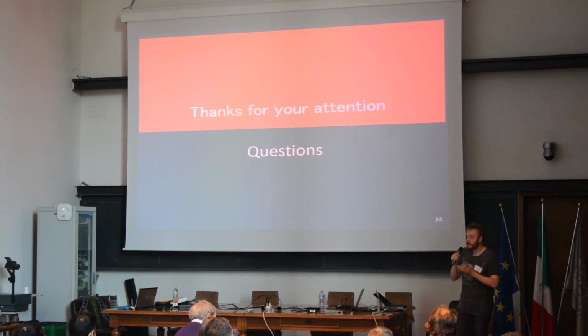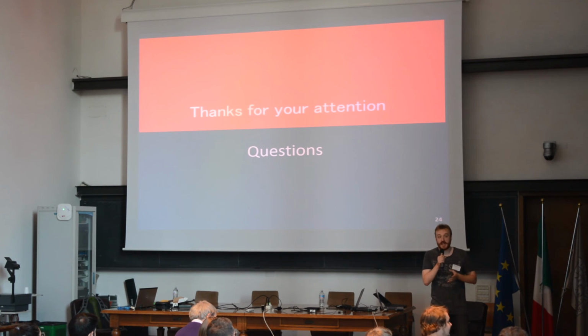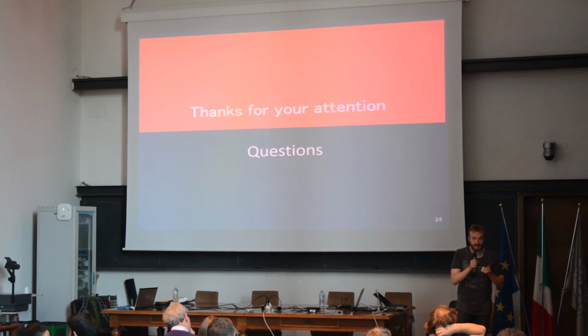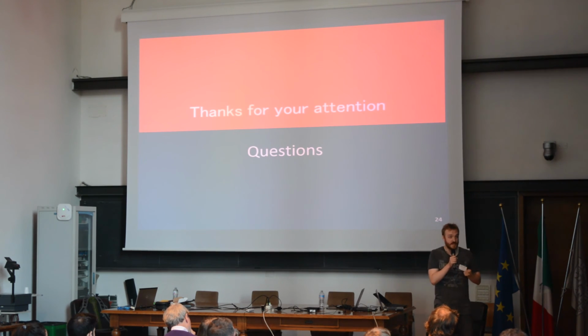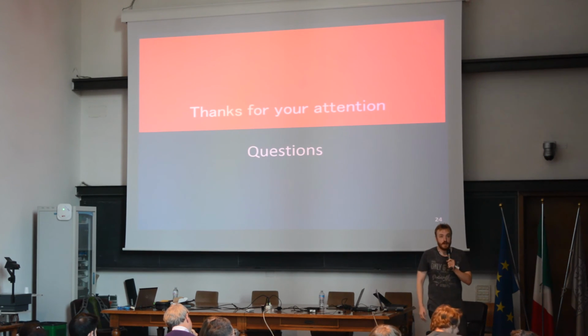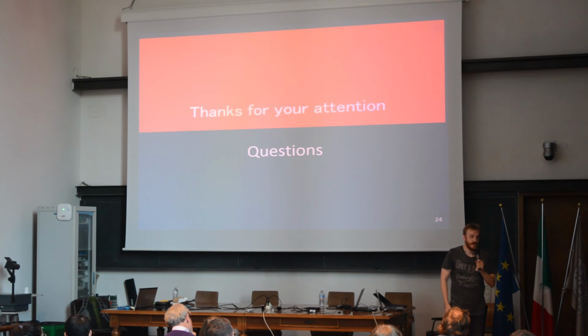Daniel knows the answer, but as you recall, I've mentioned that the performance gain will not be significant. For Dhrystone, it's about 2%. I mean, that's something, but before, using the static branch predictor, we got n cycles, and using the G-share predictor, we got 0.98 of those cycles. 2%.